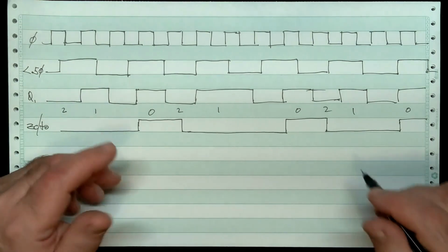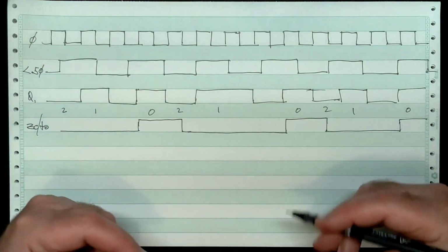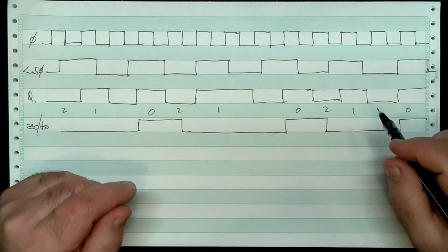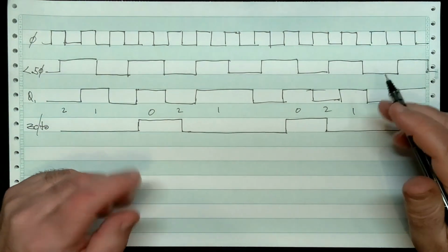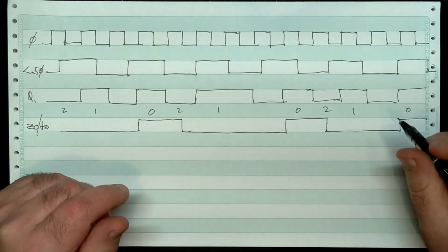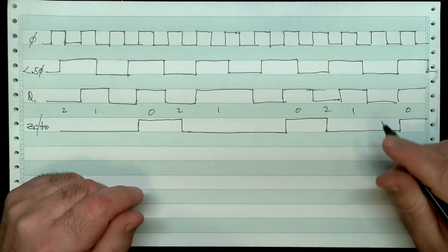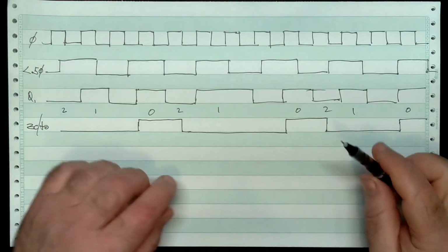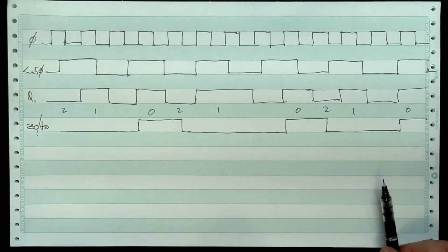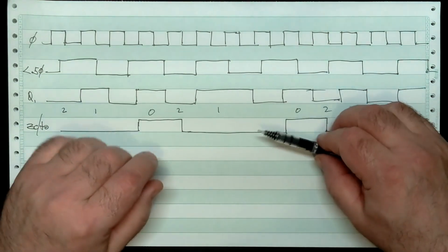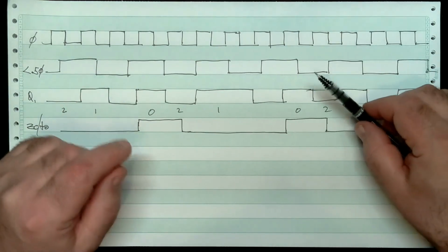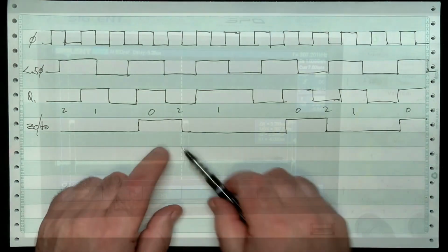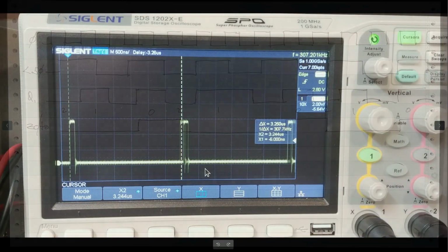And as long as that holds true, we're talking about 100 nanoseconds of jitter in a signal that's pulsing at, even if you're running at 9600 baud times 16, right? That's, well, 9600 times 10 would be 96,000, plus half again as much, 150 some odd kilohertz, right? That's not anywhere near 10 million, right? So 1/10 millionth of a second of jitter is what you're going to see on this signal here. Now we can see that on a scope if we look really close.